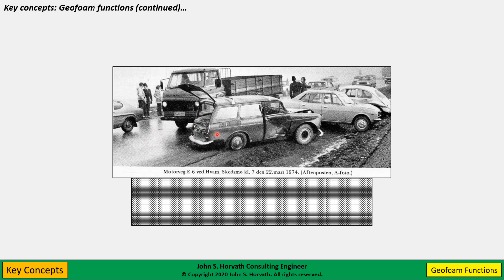And the reason this is called differential icing is because if you have a roadway that just has earth beneath the pavement, and then all of a sudden you transition to a segment that for some reason has EPS block geofoam beneath the pavement, you can have a vehicle driver who's going along, the pavement is dry and not a problem, and all of a sudden they're coming along at roadway speed, and they hit this black ice quite suddenly that has formed over the portion with the EPS geofoam.